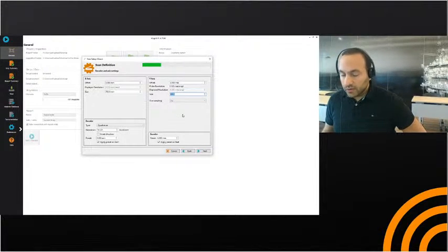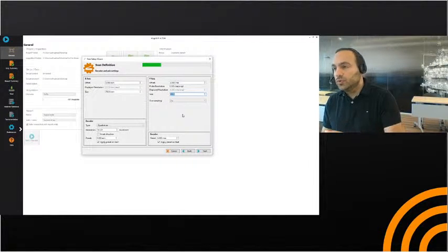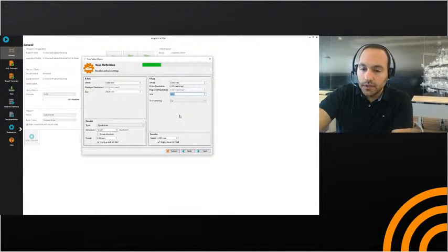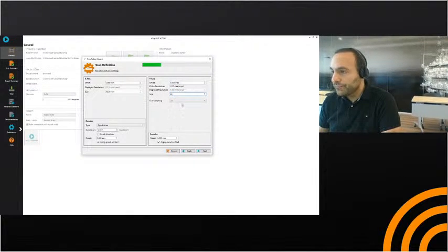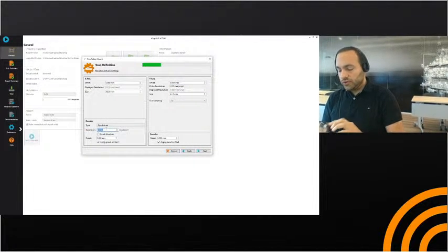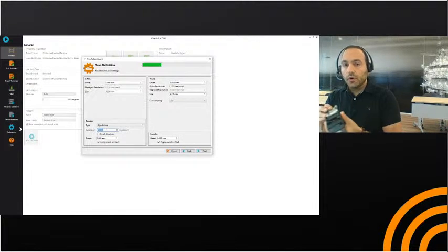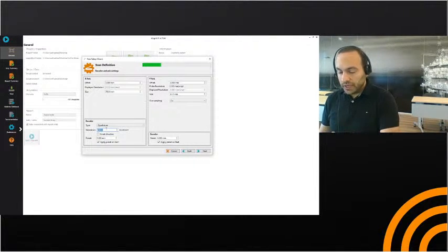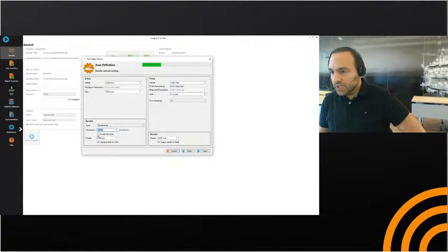Here I know that I want to try to pass two coverages of my iFlex. So let us put 67.4. And here is actually the resolution that is usually indicated on all our standard encoders. So we have 51.331 counts per millimeter. I know it's inverted direction.